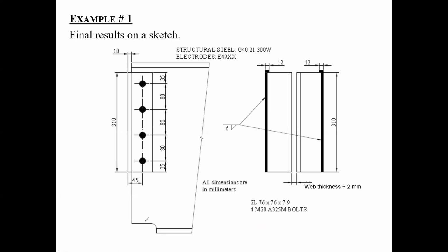And I want you to look at what we did here. In other words, you coped the beam. The reason you cope the beam is because in plan view, when you're going to be erecting your steel, here's your column, and the beam is going to have to drop. Of course, here's your angle, and here's your angle. If you do not cope the bottom, you'll never be able to drop the beam in between these two angles. So we cope the beam so that when they lower the beam into its place, this flange will not interfere with these angles, because the angles will already be there, welded to your columns.